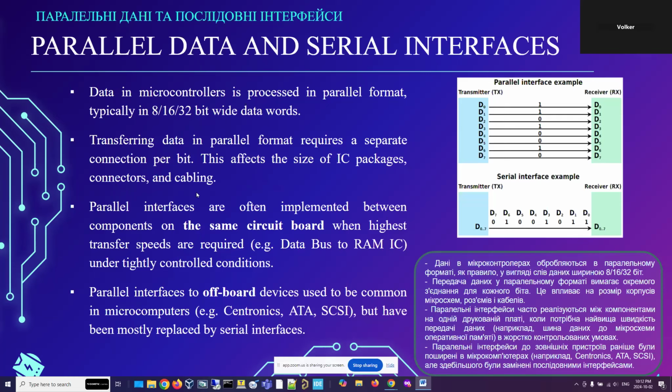Connectors and cabling, there is an issue there where the cabling increases the cost of the cables, of course, because copper is becoming more and more expensive. So if you have 8 wires or 16 wires or 32 wires, it makes a cable more expensive. And depending on the application, that makes it not cost competitive anymore. The same with connectors. The more pins connectors have, the more expensive they become. And it also has an effect on reliability. The more pins a connector has, the more the chance is given that one of those connections will malfunction.